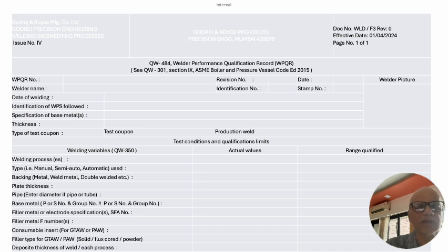Every welder has a unique stamp, which is supposed to be hard stamped after every 1 meter, or near T joints, or near the center of the long seams, depending upon the good engineering practice followed by the fabrication shop. Now the depth and the size of this stamp, everything has to be within the code permissible limits.